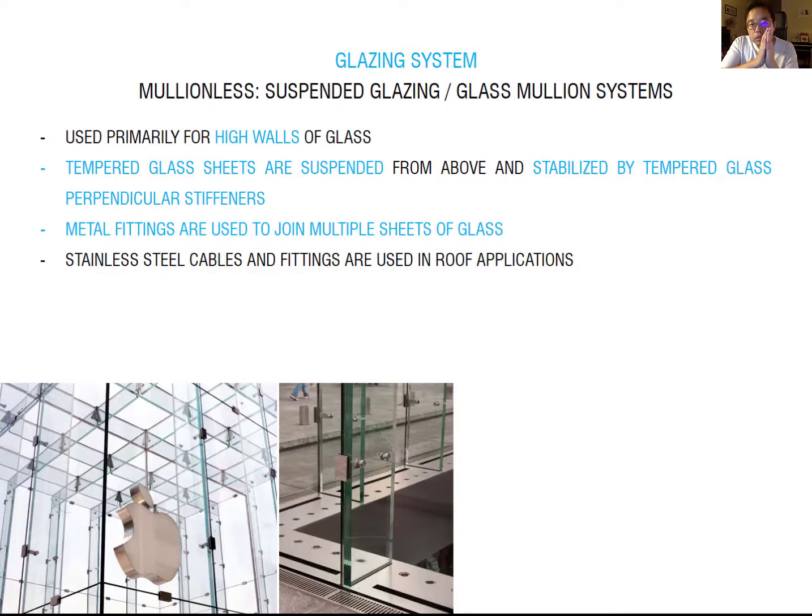And also you have to consider laminate glass. You remember laminate glass is a sandwiching panel. A single glass might be hard to support this heavy glass. So that's why it's laminated, 2, 3, 4, 5 layers laminating together to hold this heavyweight glass. At the Apple Store, they mostly have 5 different layers put together to hold this huge glass system.